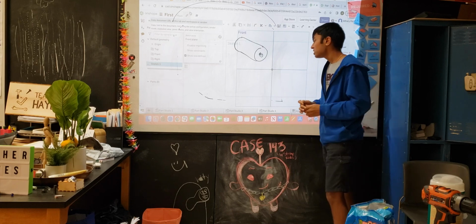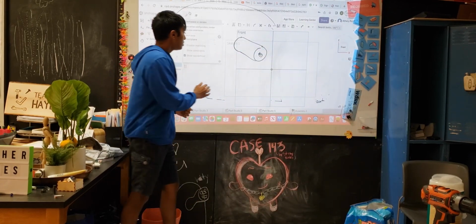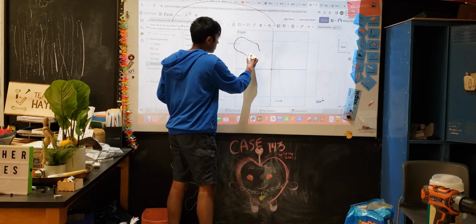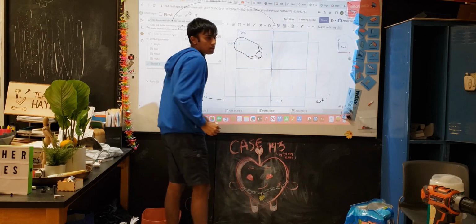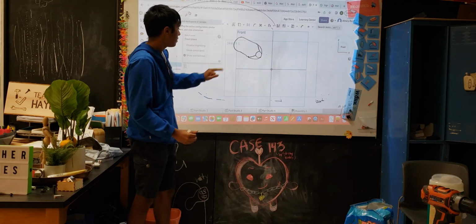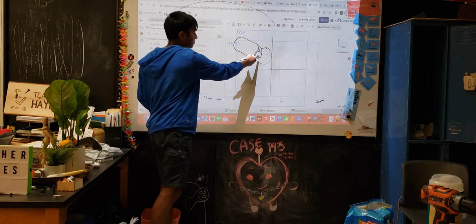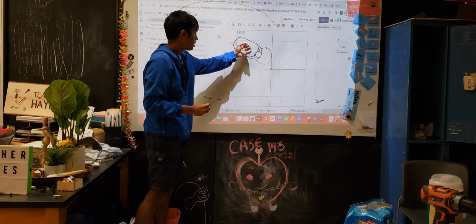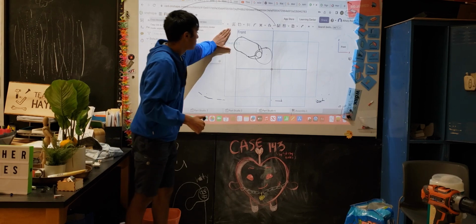Well, you actually don't want to do that, because sometimes you might want a different type of spacer. Maybe you want it drafted inwards, so that it's a little bit more conical here. Say if I have a pulley here, I want less friction from the spacer affecting the pulley. So I make it conical and have less area affecting the pulley.